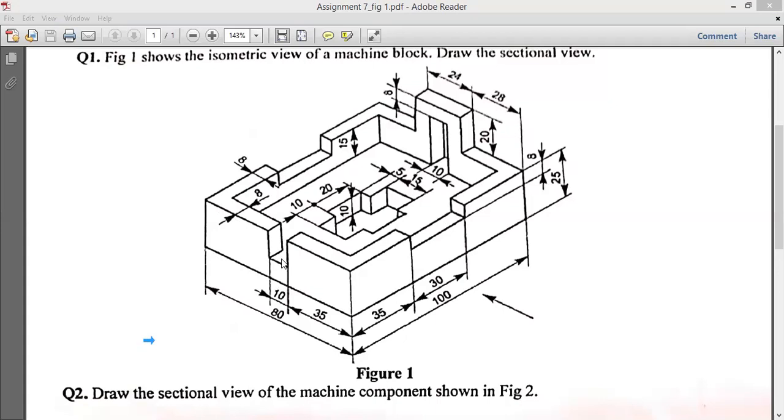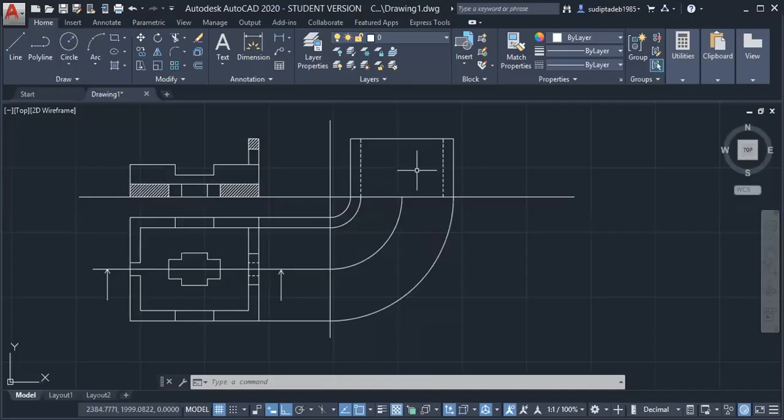That's why first we'll draw one line here itself, then I will use the hidden line to specify this line, it will not be up to the last, up to the base. So use the offset command, O, enter, distance is 10 from the ground.